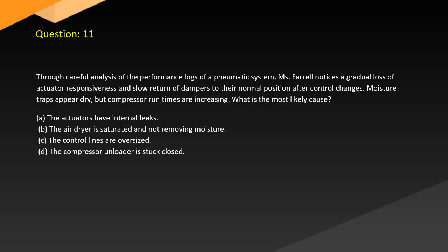Question 11. Through careful analysis of the performance logs of a pneumatic system, Farrell notices a gradual loss of actuator responsiveness and slow return of dampers to their normal position after control changes. Moisture traps appear dry, but compressor run times are increasing. What is the most likely cause?